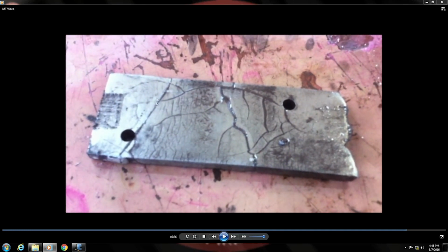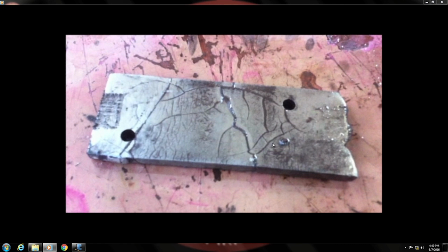So, it is advisable to magnetize the part in different directions. You could see a lot of cracks in different orientation. This is differently oriented compared to this, then you have a big one over here, and then again a perpendicular crack like this. And then you have cracks which are at an angle close to 45 degree like this. Okay. So, that is why, as I said, it is always better that you magnetize the part from different directions.